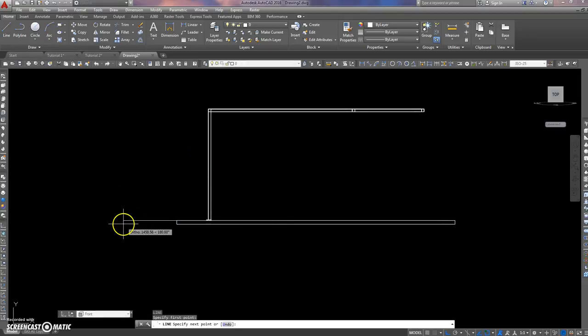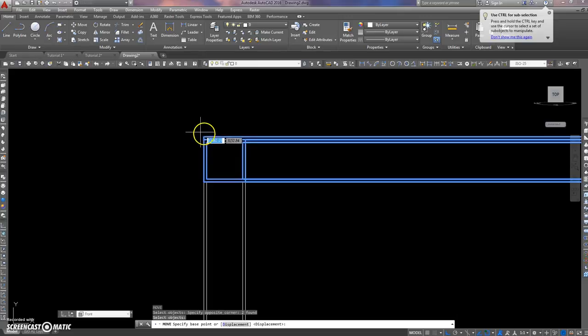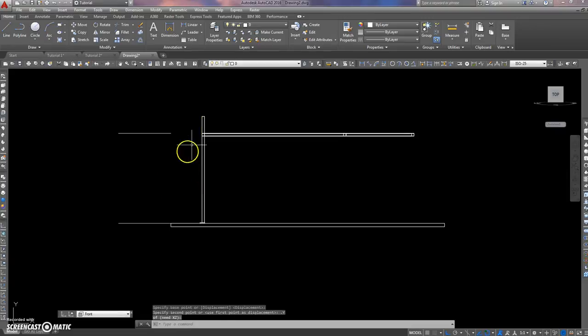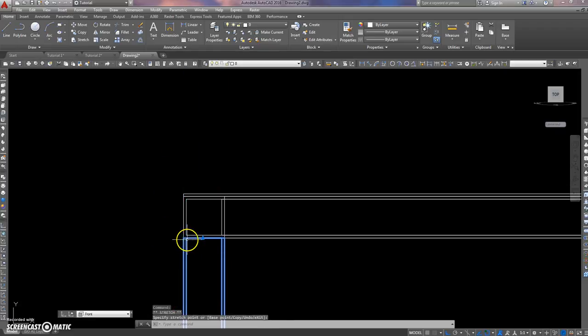And now, if I wanted that to be 2000 from the floor, the actual floor there, so offset 2000. That's a pretty low platform. Hang on, we'll make it 2500. Offset 2500, just to make it a bit more realistic. And there it is. So if we move all of our top platform bits, using that as our reference, dot Y of the end of that comes to there. Now, that's where leaving this as it was a good idea, because all we have to do is pull that down, and they pull down rather nicely.